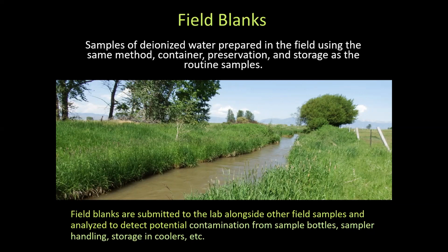So since this is analyte-free deionized water, you would expect that field blanks would return results of non-detects from the lab, and if any analyte is detected in a field blank, it can lead you to contemplate what might have caused that contamination and take measures to fix the problem.